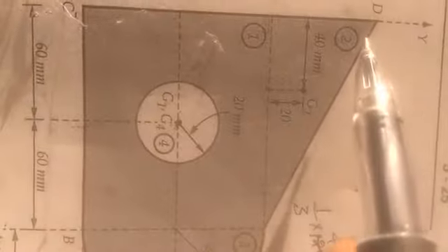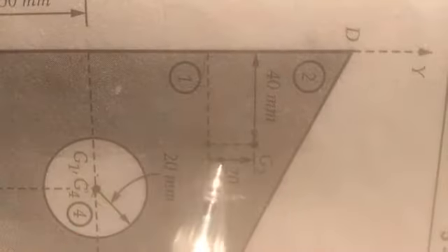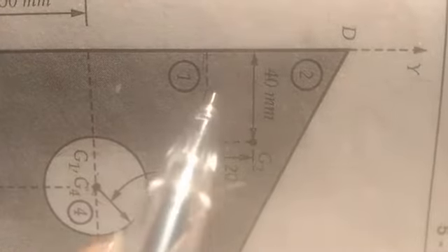But what about the y distance? The height of this section is given in the question. You can see, observe, the height is 60 mm. The CG arises from here to here. If you come from this side, it will be 1/3 only. So if you come from the origin, either in the y direction or the x direction, the CG arises at the 1/3 distance. So again it is 1/3 of the height of this triangle, that is 60 mm. So it is one third of 60.